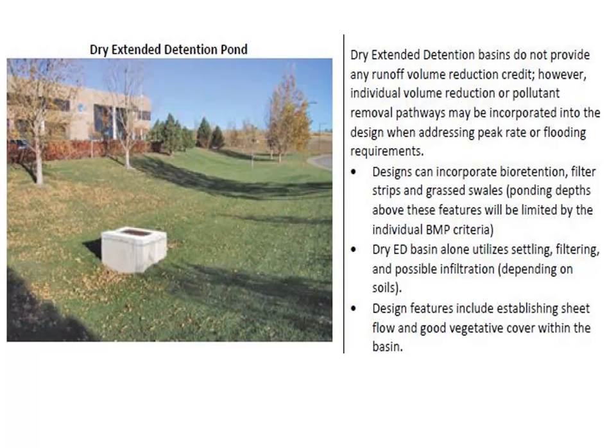A dry extended detention pond is a pond that is meant to be dry most of the time, except when you have really wet weather events, then the pond will fill up and it would take a while for it to drain. What they'll do is put an orifice, or in this case it could be acting as a weir. This riser here could be that the drain is on the top, and so water will flow in through the riser only when the water level gets to a certain elevation, but otherwise it would just be infiltration into the grass that dissipates the water in the pond over time.